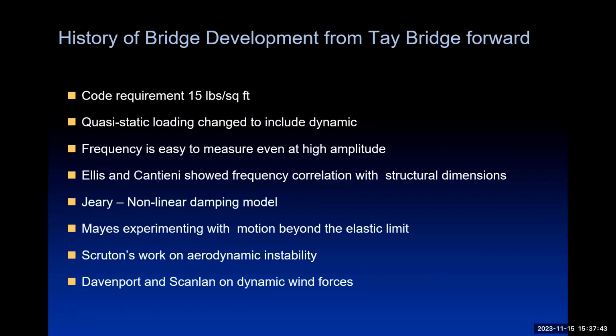What this means is that you have the possibility of instabilities, aerodynamic instabilities, caused by the bridge having very low frequencies of resonance and the wind having a lot of energy in it at very low frequencies. If we'd understood that when the Tacoma Narrows was built, we might have avoided that problem. Well, it went further.